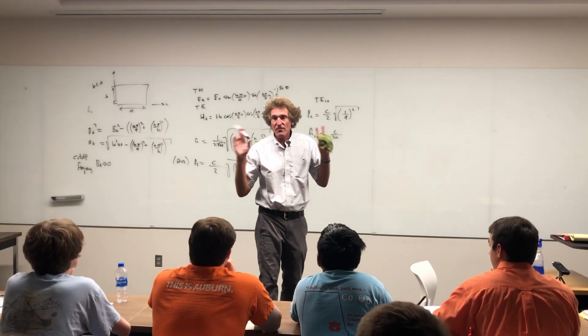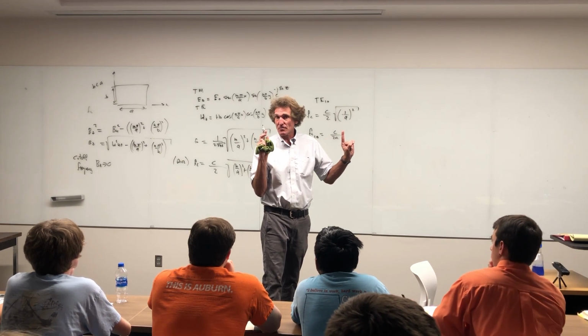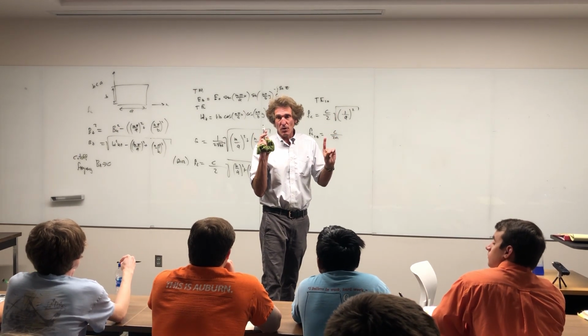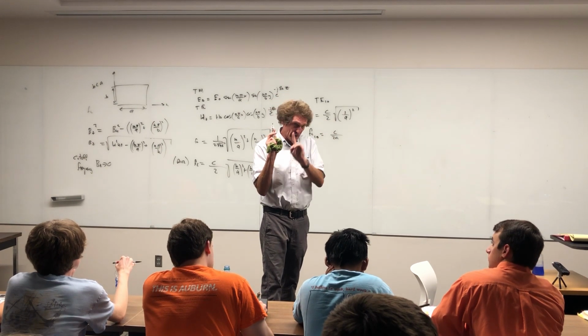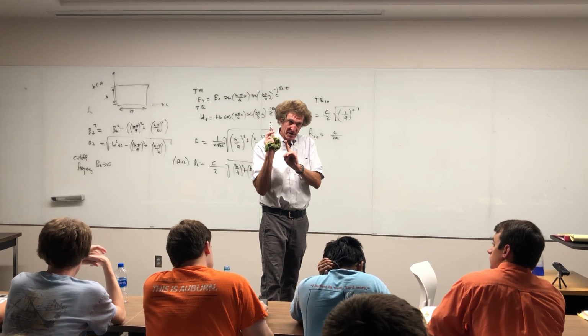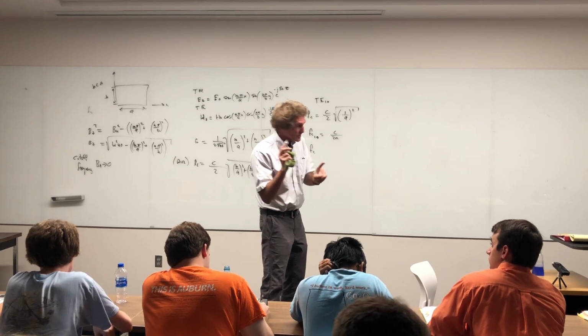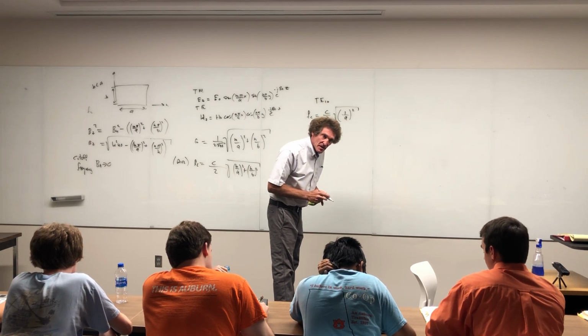In almost every case, for normal waveguides, they make it so the first lowest order mode is a 10, and then it's 20, and then 01, all right, where n would be 1 and m would be 0. Do you follow me? And they're all TE. Correct, class? Just understand, I'm trying to give you a heads up, and we'll spend more time on this. So, he asked me for 9, right? 8, but 8.